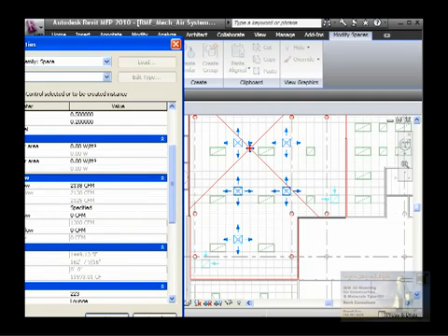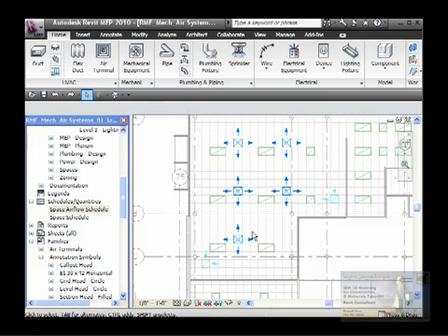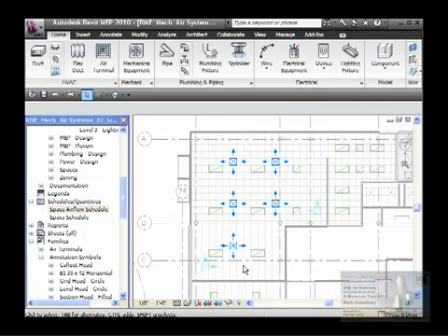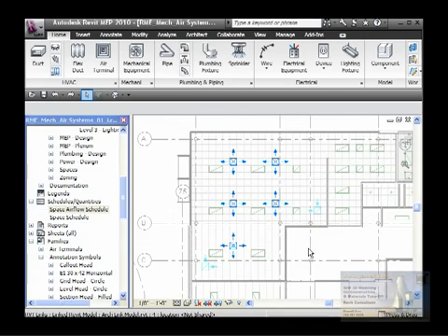However, right now my return flow is only 1300 and my supply 2138, so I'm way less on the return airflow. So if it needs to be the same number, obviously we need to put more air return, but I don't want to worry about it, because like I said, mechanical engineering is going to do this, and they will, or you will. Okay.